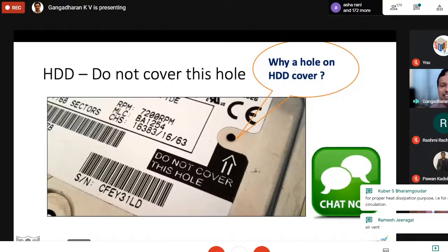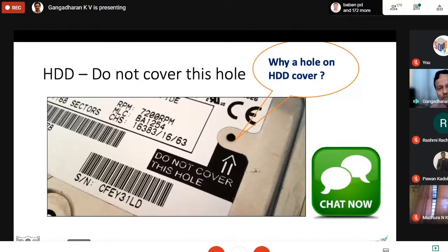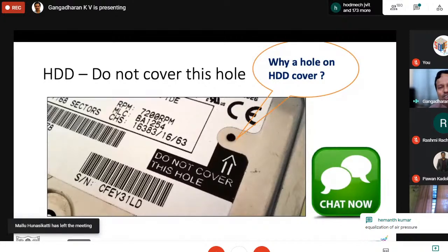So during this, the air should go out, and when you stop, the air pressure inside will be less because there is no centrifugal force, so the air has to come in. So this is called a breathing hole. And a breathing hole is very, very common in crankcases, compressor cases, and all that. But even when it is an embedded system like this, a breathing hole is required.